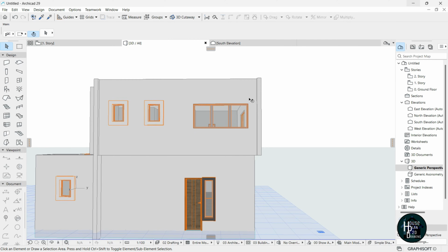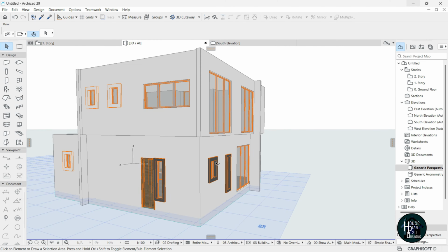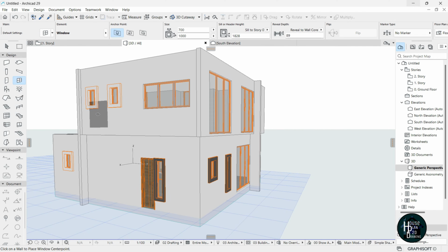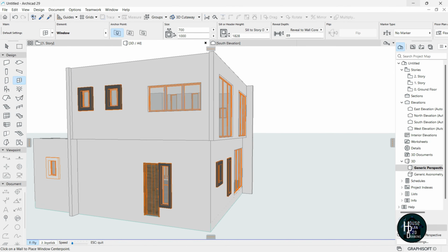Okay, so it's going to have something as simple as this. You can decide to add a coping to it. Okay, so for this coping and this coping, they're going to be dark copings. So what you want to do is hold Alt, select this toilet window, press Ctrl Alt, select this and select this. So that changes into a dark coping for us.